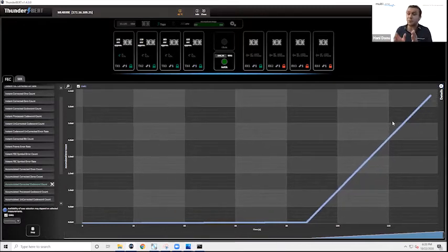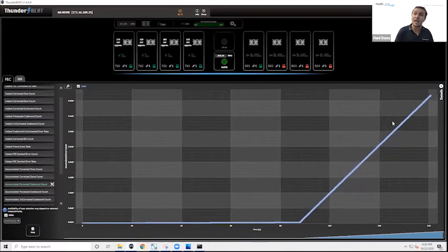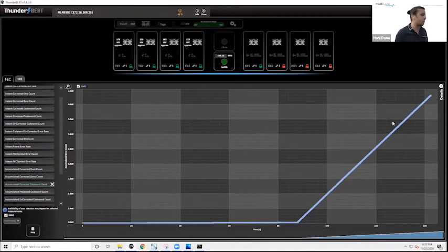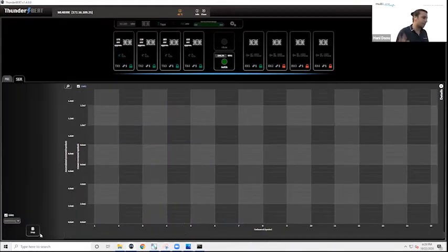And to be able to give you a full depiction of that marginality, we have an SER measurement, a symbol error rate measurement. And by the way, these are the same measurements, the same sort of visibility that you would get in, let's say, a 400 gig or an 800 gig switch, simply because they are the key figures of merit for a healthy link. In fact, I will take it a step further to say we have more measurement visibility than the switches do, simply because this is our primary focus.